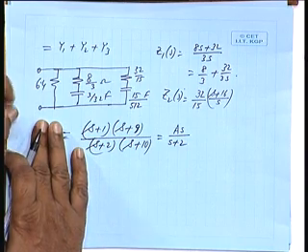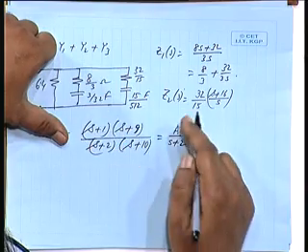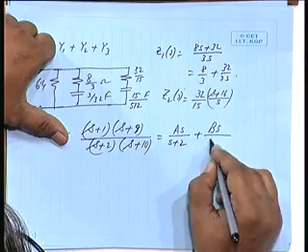Suppose I have this given as an admittance function Y of s, then it is an RC network, is it not? For Z of s, the one closest to the origin should be a pole. That means, for Y of s, the one closest to the origin should be a zero, and we have got factors for that. Suppose Z of s is given in a similar fashion, for which we have already factorized in this form, like the previous one.